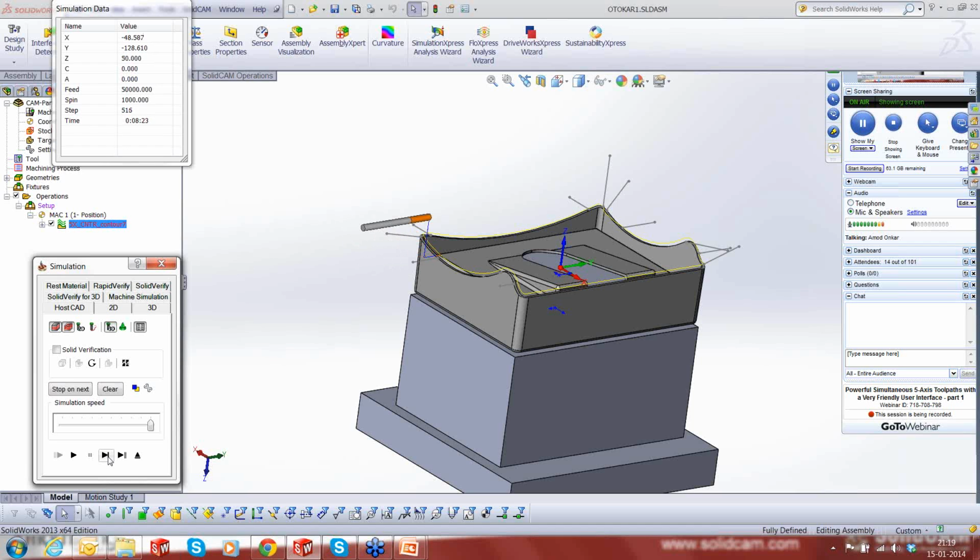Perfect. That's it. So what this does is basically it allows you to program your vacuum form parts or trimming parts very quickly. And you really don't have to depend on the surface normals, because in many cases the surface normals are not the way to cut it, because you have holding fixtures that are holding the part below. You don't want the tool or the head to go and crash into the holding fixture. You want to control the tilt, and the tilt lines are the best way to control the tilt very easily. We didn't pick any kind of surfaces. We just picked the curve and the tilt lines, and we have a result.